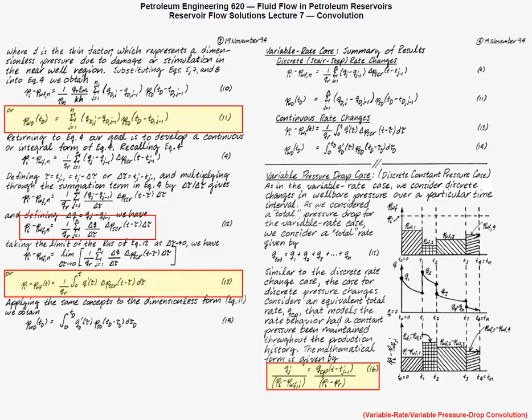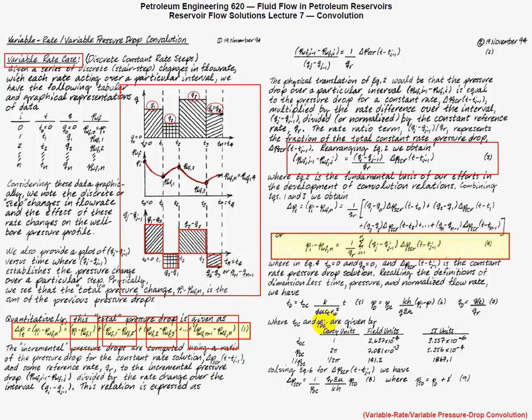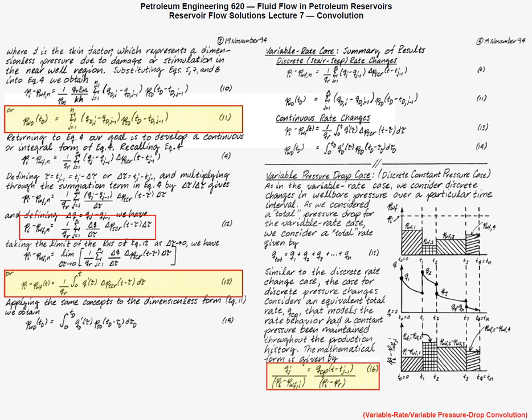Okay, that's the real pressure drop, not the dimensionless pressure drop. That's the real pressure drop for the constant rate case. So the ordinary dimensionless pressure that you're used to using is PSD. When you multiply PSD by these terms, like this, you get delta PSCR. Okay? That's where that comes from. So that's a real domain form, and the other is a dimensional, or sorry, it's a field variable form, and the other is a dimensionless form.